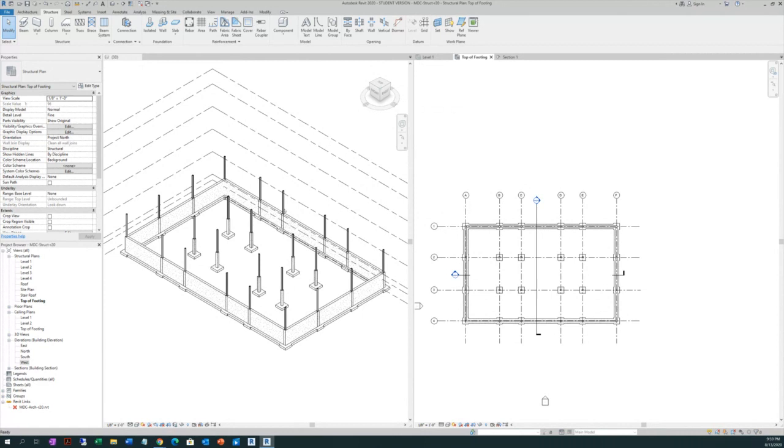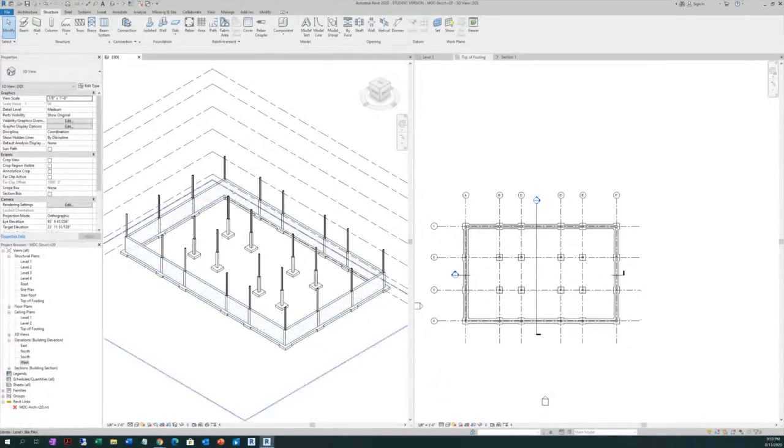Okay, and the roof, but the roof will be on the architectural part. Now, remember something. This part belongs to the structural. If you are working with a firm, make sure that you coordinate with the structural. Because if you send this part included on your architectural file, the structural cannot do this footing because it needs to be hosted, done by the structural. So keep that in mind, just for coordination, okay?